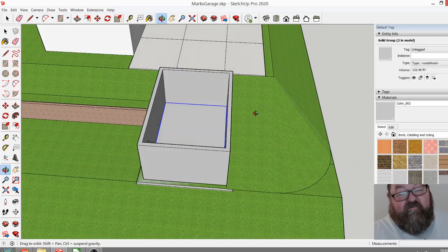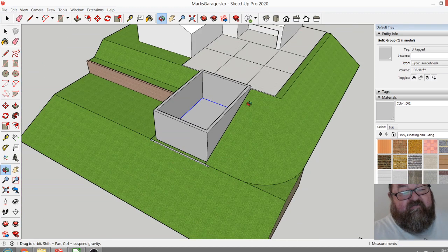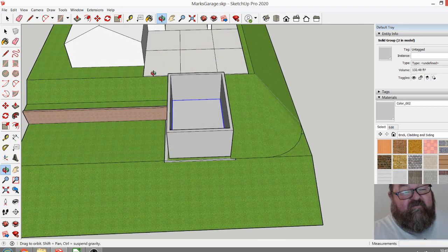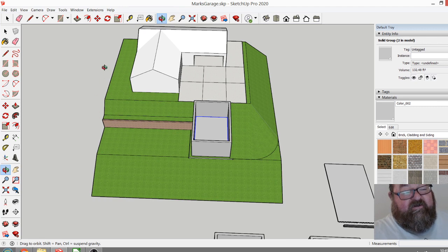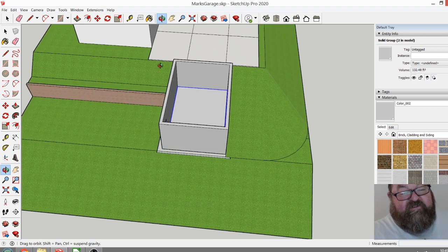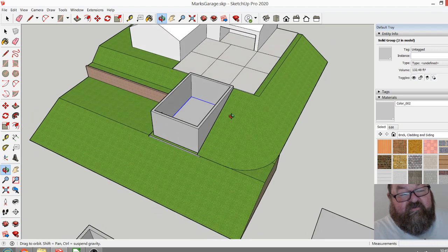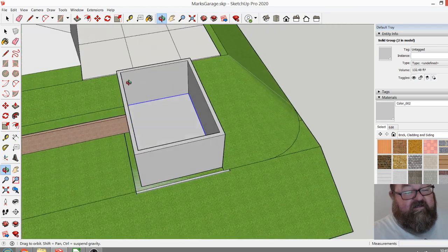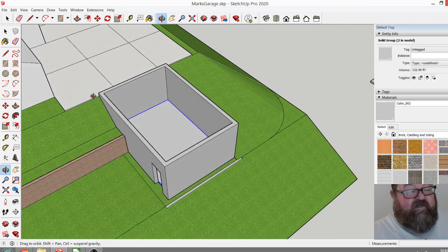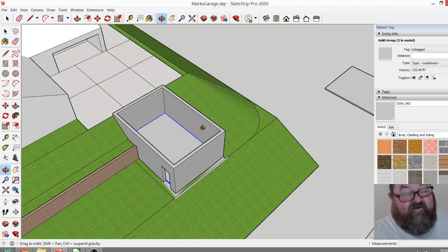He was worried about having room to come down beside it right here for equipment and stuff. You don't have to worry about that too much as long as you've got room to get around it. Even if you had to come around to this side of the house, your yard will survive eventually. You can always fix your yard, but you don't want to build some tiny little garage here and later be regretting that. So what you want to do is find out where your setback is and run this thing all the way over to the setback, and then see what kind of room you can tolerate right here. Coming over here, I would make this thing at least 20 feet wide if I could.